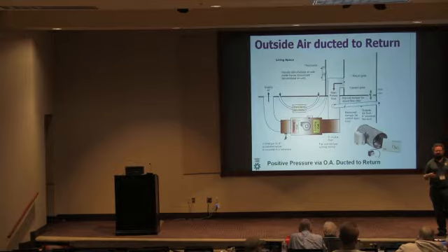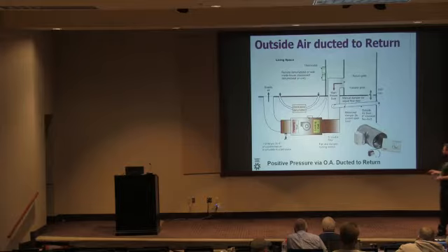And what happens is, if you do it intermittently, if you're only ventilating 30 minutes out of every hour, you have to double the size of the duct. So I think probably people are going with smaller ducts and longer run times. But if you go with the probably slightly more expensive controller, the occupant can determine more or less for themselves and not have it set to a fixed run time.